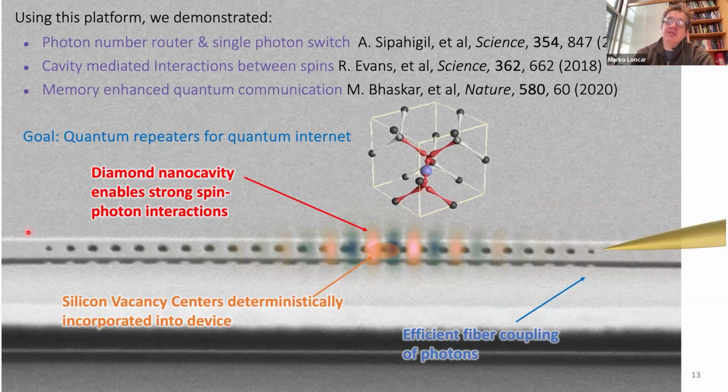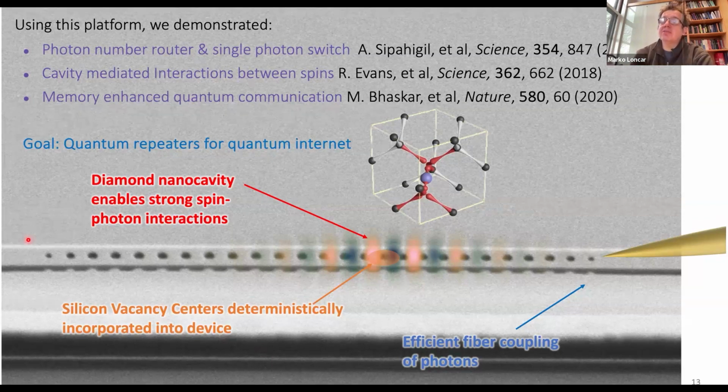This diamond fabrication is very non-standard at the moment, but it can be done in thin films, as somebody asked. And then another nice thing is going back to what we talked about earlier, bringing light on and off chip. If you have single photon and all information is embedded in single photon, you better not lose that photon. So we need to have 99.9% ideally coupling efficiency to optical fiber. And the way we do this is take fiber from like 100 microns diameter, we taper it down to a point basically, and then bring this point to a diamond waveguide and touch it.